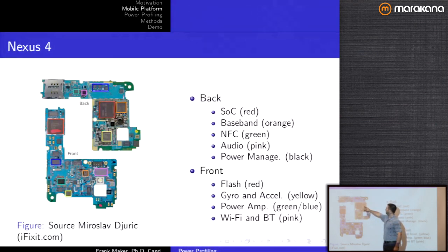These tend to be an ARM processor as well, but a little bit slower because they don't need as much performance. Because this chip is a real-time chip, so everything has to be done at a certain time, and there's deadlines that need to be met by the software. That's what real-time means. Whereas this chip is where your software goes and the operating system, and all that stuff is just best effort. So that's one of the reasons they split it into 2 chips.